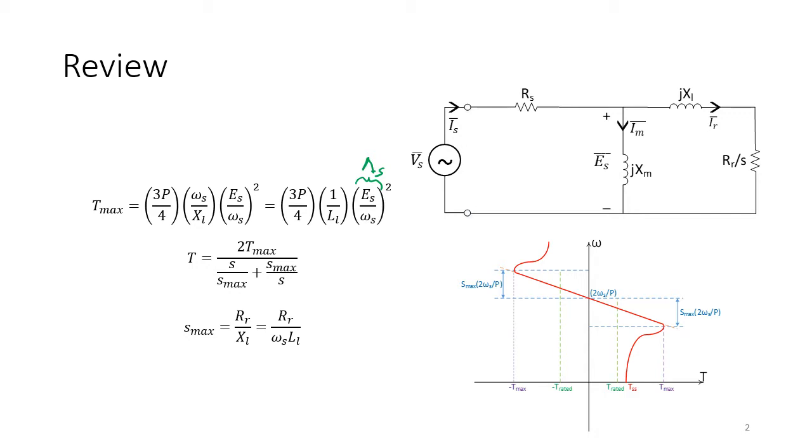We talked about how close to the synchronous speed, somewhere close here, it shows almost linear behavior. But when we start to deviate from the synchronous speed, we also start to deviate from the linear behavior, and you can see it there. We found that S max for both motor and generator mode are the same, and we found that the standstill torque, or start torque of the machine when the machine is stopped, not rotating, TSS, is much smaller than